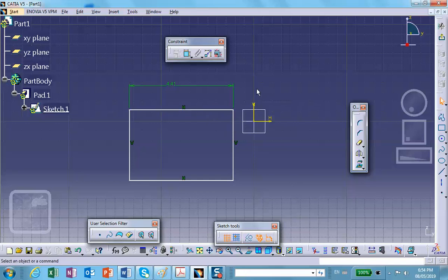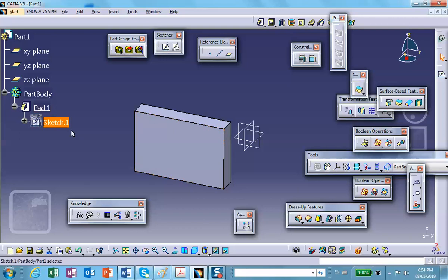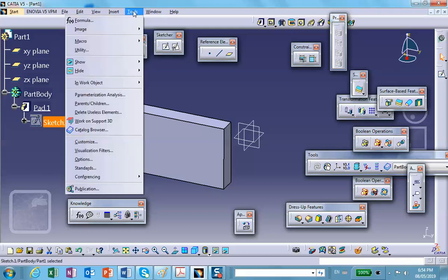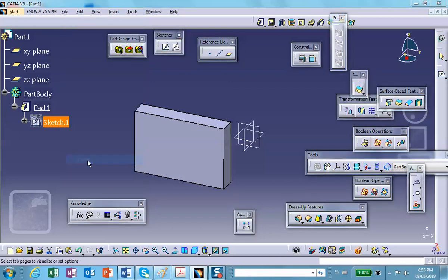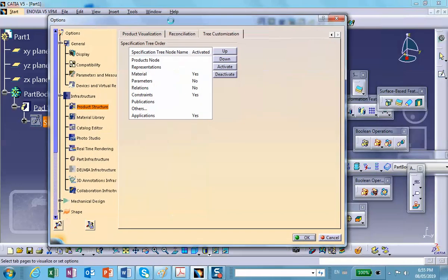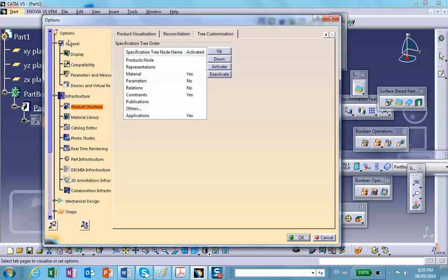Suppose that we wanted to change our units to maybe millimeters as far as length goes. So here's what you do. Tools, options, open this dialog box where you can do basically it's creating a CAD setting file. Okay, now first of all, if you select any of these branches,